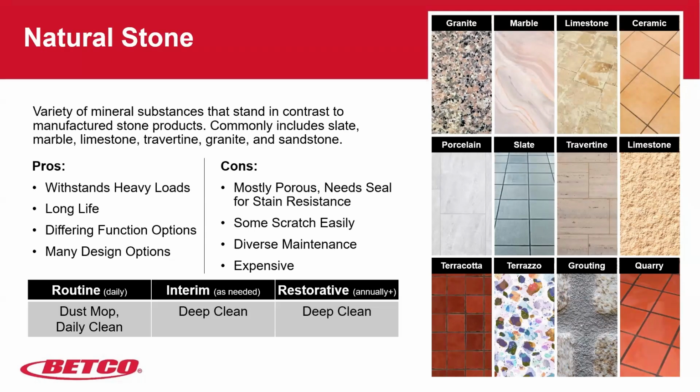Natural stone. We're seeing more and more natural stone being brought into our facilities, and obviously they are all a little bit different. You take marble, for example, compared to a travertine or a limestone. Totally different types of substrates. The marble is very hard, very non-porous. You don't want to use anything too high or too low on the alkaline scale on marble. Limestone is very porous. So the techniques that you use to maintain these floors are significantly different when you're going from one substrate to another.